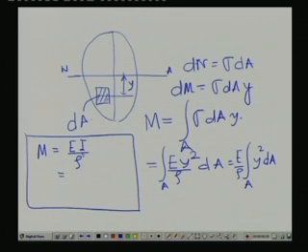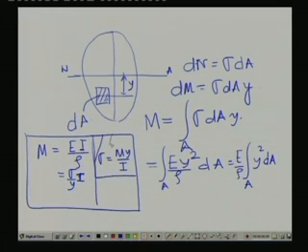If we replace it, then we got earlier that sigma was nothing but E y by rho. So, sigma by y comes out to be E by rho. So, that means sigma by y into I comes out to be the expression, and so we get sigma equals to M y by I. So, this one comes out to be a beautiful relationship, widely used in the bending of beams.